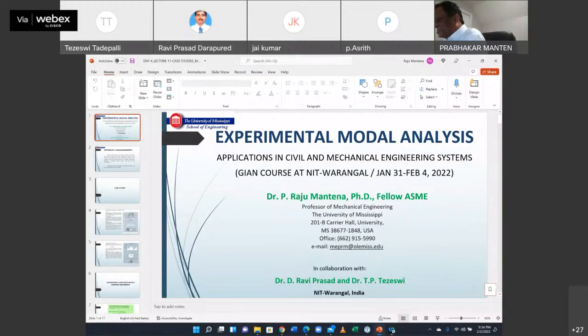The energy content is expected to be maximum for any curve. Again, this all comes from electrical engineering terminology for a given signal, where the energy content would be at its maximum, and from that knowledge the content is focused not at the peak of the frequency response function but around the 3 dB level. If you are using a linear scale, it is 0.707 of the peak. If you are using a log scale, which is normally used, it's a drop of about 3 dB.